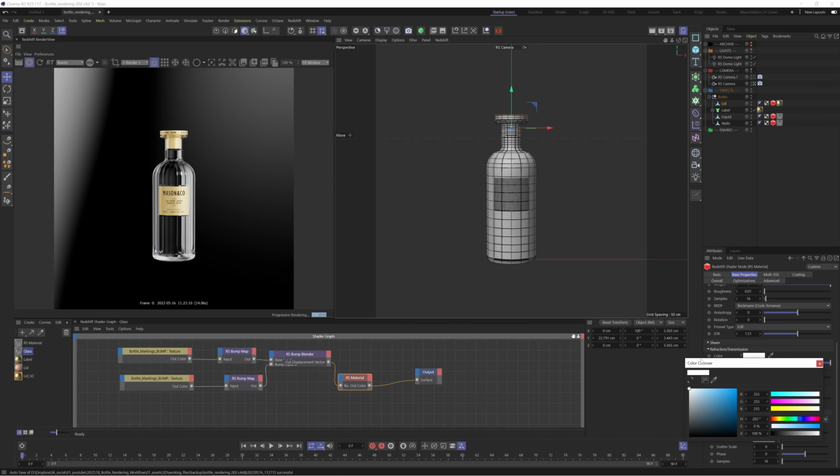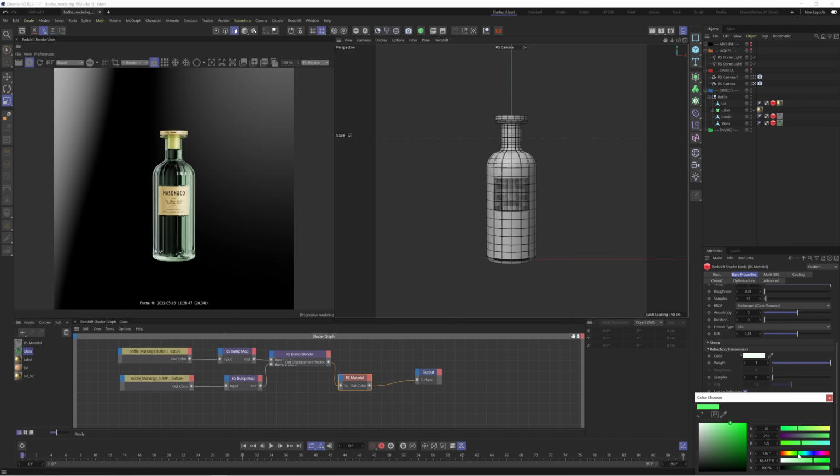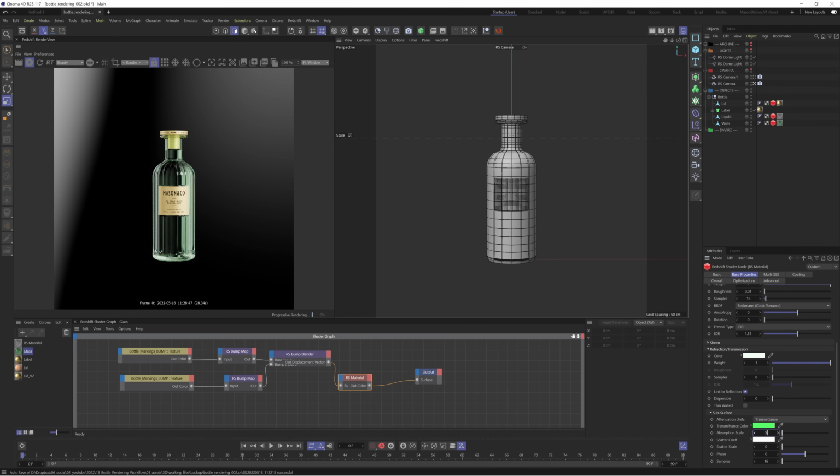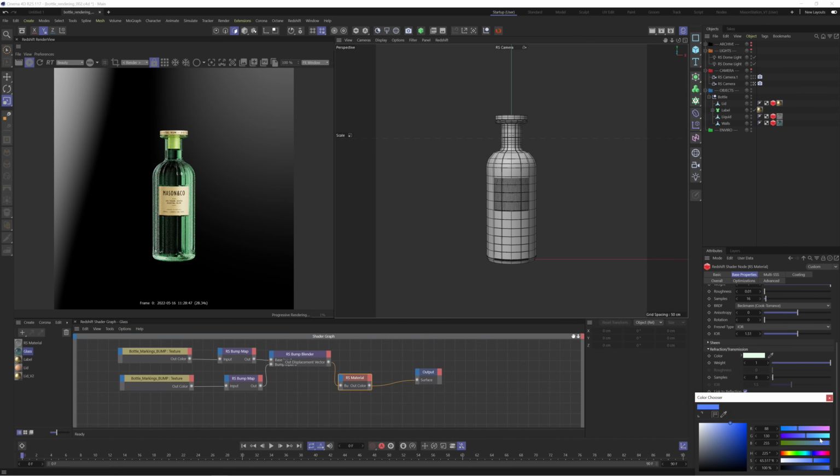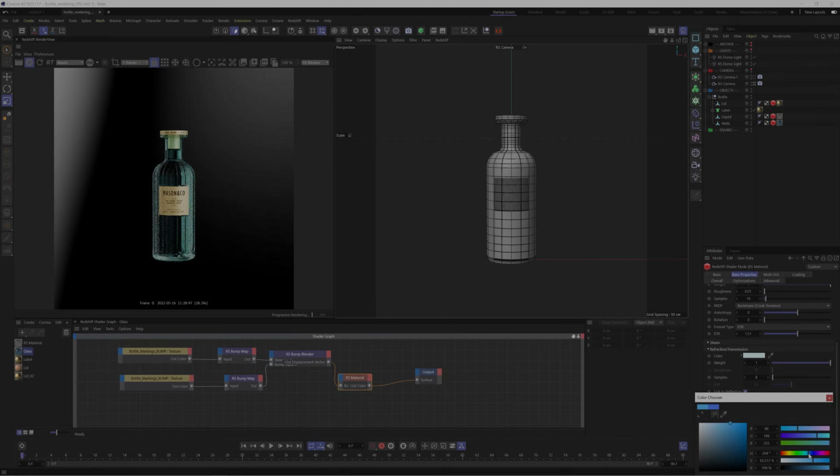Just dive into the refraction color and add some hue and saturation. You can also add a similar shade in the transmittance color so that the tint becomes more saturated within the object. Let's leave this on a bluish tint for now and let's dive into the lighting.